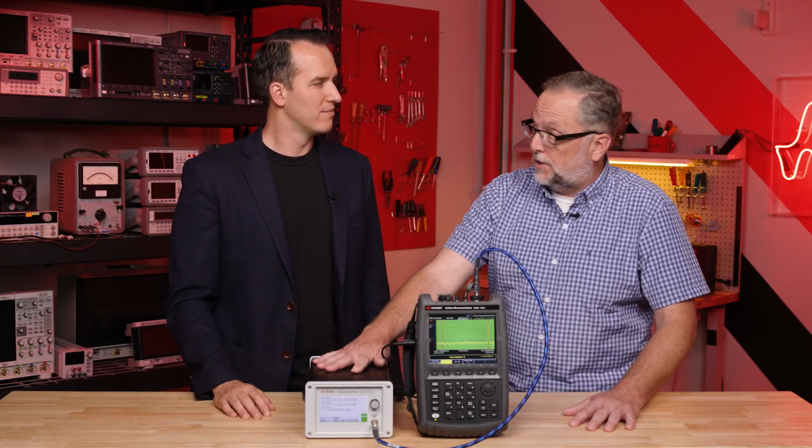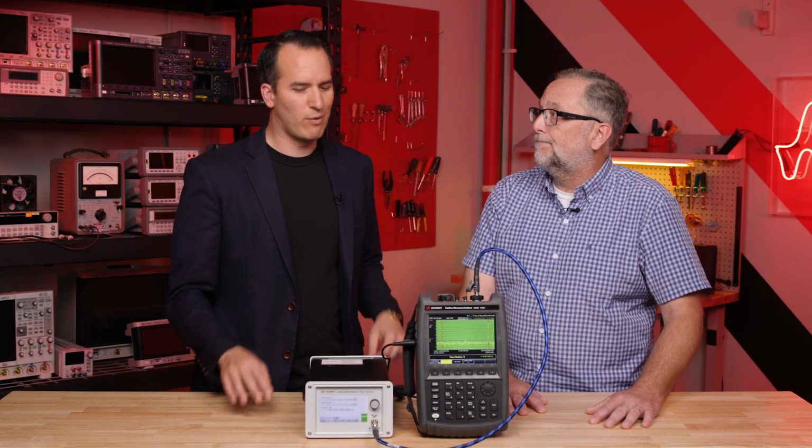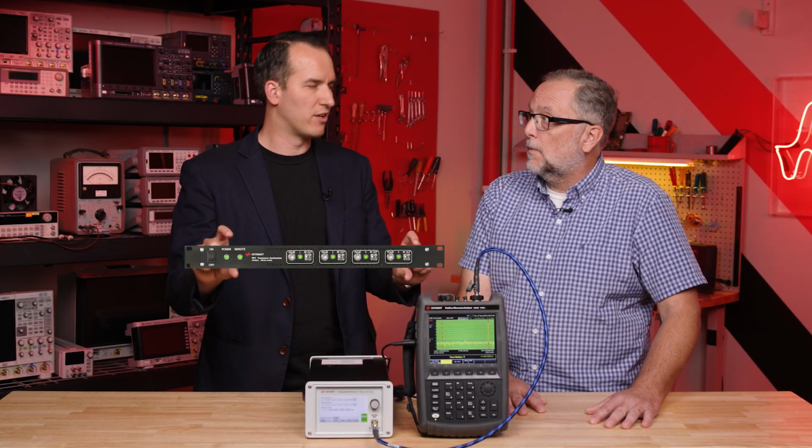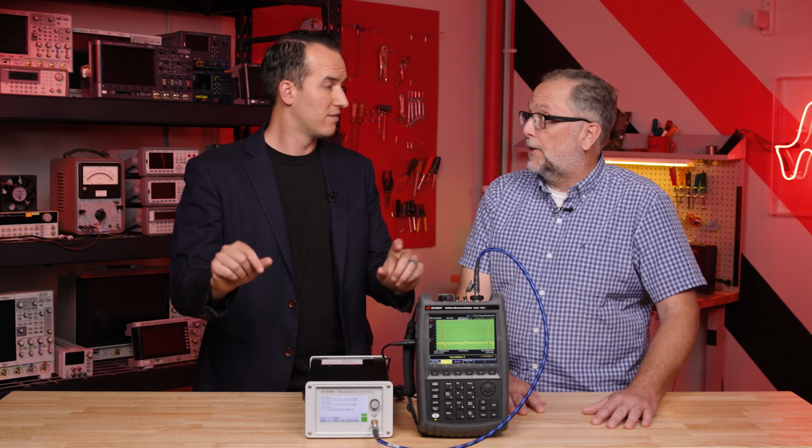Yeah, great question. So there are rack mount kits for these desktop versions of this instrument, but often, as you said, people are building ATE racks, and they want to make those test racks for production as small as possible. So we actually have a 1U version of this generator, 1U high, 19-inch rack width, very small, but still provides all the same capability that you have in this desktop version to support our production test customers. What frequency ranges are we looking at for the 1U? All the way up to 26 gigahertz. Okay, pretty fast. Yep, in a very, very small package.